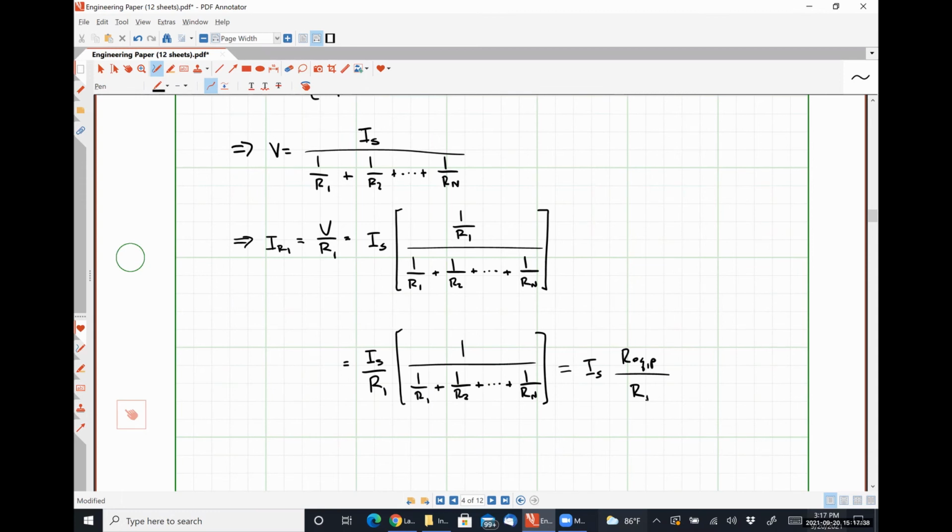And the reason why I don't like teaching it is because it winds up having the resistor you're not interested in the numerator divided by the sum of the resistors. So it's a really weird rule set to think about. In my way, in the numerator I have the reciprocal of the resistor I'm interested in divided by the reciprocal of all the resistors in parallel, which is very similar to how it looks for voltage division, where it's the resistor I want divided by the sum of the series resistance. If I show you that other method, then you have to start thinking about, well, what's the resistor I'm not interested in, and where does that fit into the equation? And it gets all wackadoo real quick, okay?